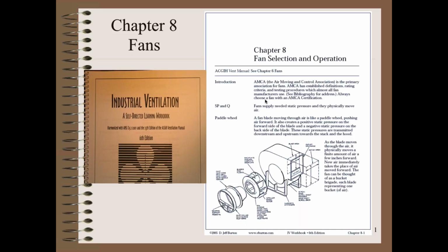Then it has to take that air and push it out and get rid of it outside. So very frequently, this is going to go to another duct on the other side. Maybe a duct coming out, an elbow, a duct going up, going out through the roof. So you're going to have some resistance to flow going out. Now, if I don't have that ductwork connected, what's the static pressure here?